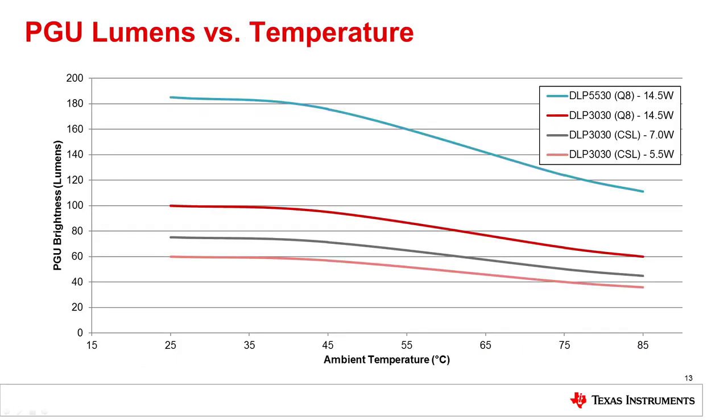For an automotive HUD system, it is important to consider how LEDs perform across the entire automotive operating temperature range, as HUD systems are usually operational up to 85 degrees Celsius. As temperature increases, LED efficiency decreases, and HUD brightness can change. It is important to choose the right LEDs to ensure the HUD achieves the maximum brightness targets for all temperatures.